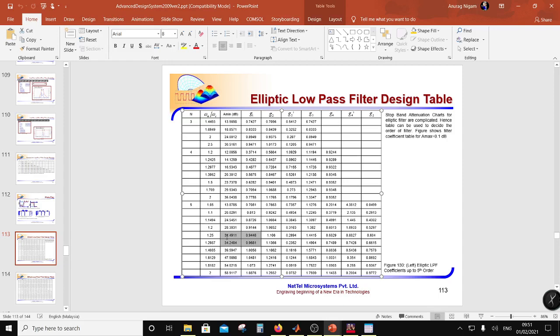At 15 gigahertz you want 31 dB of isolation, so you will implement this filter. This will give you a low pass filter. I'm going to design this filter and I will keep the order always odd. This is for a ripple of 0.1 dB on the pass band, right? So that's the table.